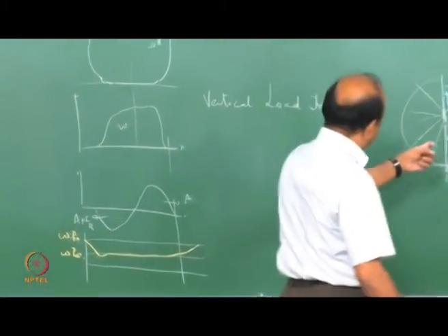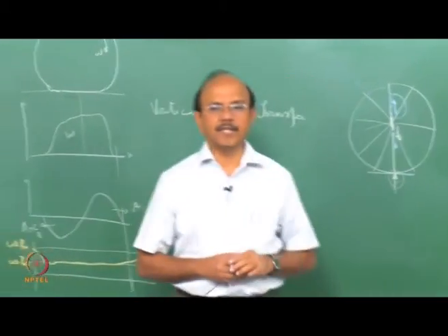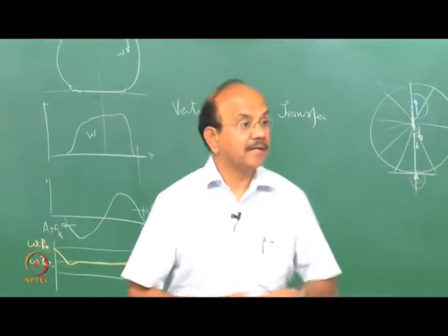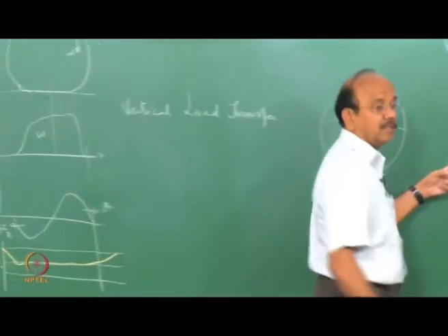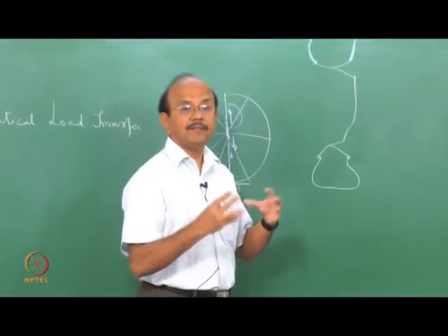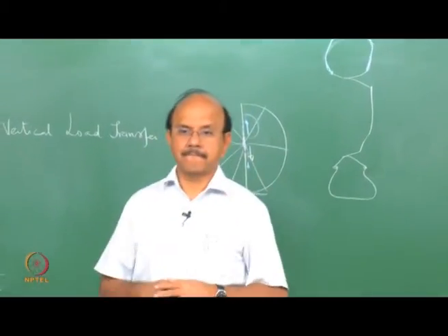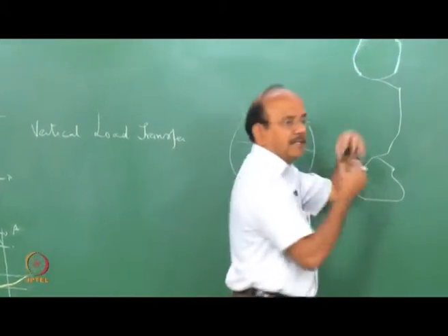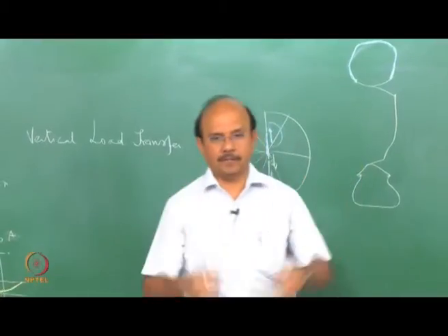Here the tension in the spokes is given when we assemble the wheel. Here the sidewall gets the tension from the pneumatic pressure, in other words, the inflation pressure.